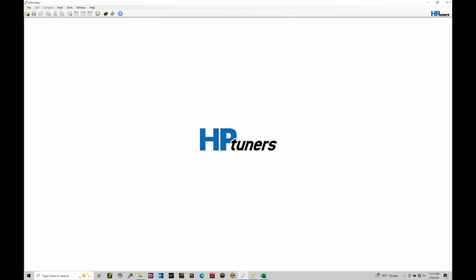We're also going to be working in our Excel spreadsheet calculator from our training course. This has a dedicated page to recalculating and allowing you to retune the O2 transport delay based on your O2 time constant table and your logged O2 transport delay total value that we can get through our VCM scanner logging. This will make more sense as we go through the tutorial, but let's jump in here and open up our file and locate our O2 transport delay table, and talk about this a little bit further.